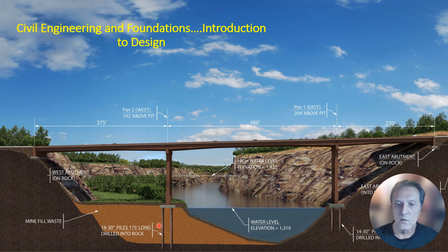That's not good. That's not suitable material for a foundation. It's loose, not compacted, not cemented. It's got voids in it where groundwater can seep in. It can settle and is entirely unsuitable for a foundation. So what you want to do is penetrate through that bad material and put your deep piling type foundation into stable bedrock down below.